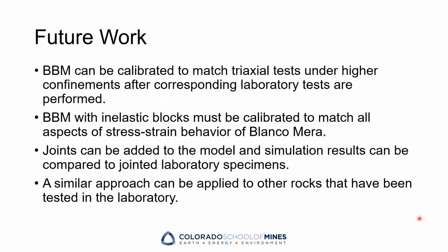However, inelastic blocks are required to match post-peak behavior as well as pre-peak behavior under higher confinements. Inelastic means that the blocks are able to break, so inelastic models more accurately represent real life, where individual mineral grains crack under stress. So my next step will be to restart the calibration process using inelastic blocks.